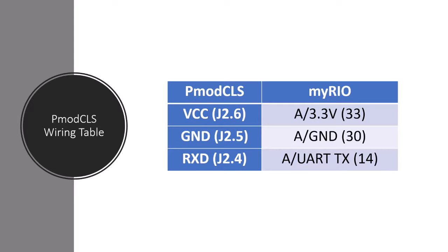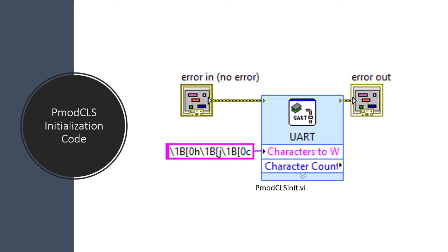These are the electrical connections used between MyRio and PMOD CLS in this project. Along with the initialization of channels associated with PMOD keypad's columns, MyRio's UART output to PMOD CLS is formatted. The commands given wrap text at 16 characters, clear the display and home the cursor, and turn the cursor off. Throughout the game, all messages sent to the PMOD CLS will wrap to the second line on the 17th character